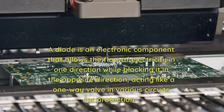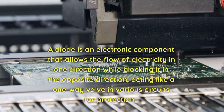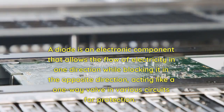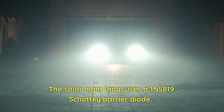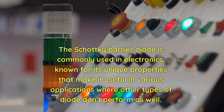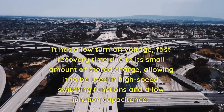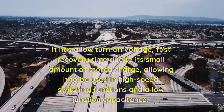Diodes. A diode is an electronic component that allows the flow of electricity in one direction while blocking it in the opposite direction, acting like a one-way valve in various circuits for protection. The solar night lamp uses a 1N5819 Schottky barrier diode. The Schottky barrier diode is commonly used in electronics, known for its unique properties that make it useful in various applications where other types of diode don't perform as well. It has a low turn-on voltage, fast recovery time due to its small amount of stored charge, allowing it to be used in high-speed switching functions, and a low junction capacitance.